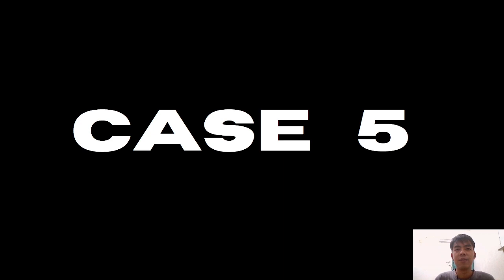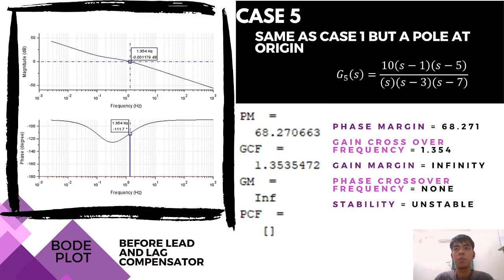For case 5, the condition is same as case 1, but a pole at the origin. The G5S is the formula we generated. The phase margin from the formula we generated is 68.271, and the gain crossover frequency is 1.354. The phase plot doesn't intersect with the negative 180 degree, same as case 2, so we don't have a phase crossover frequency. Therefore, the gain margin is infinity, and this system is a so-called unstable system.